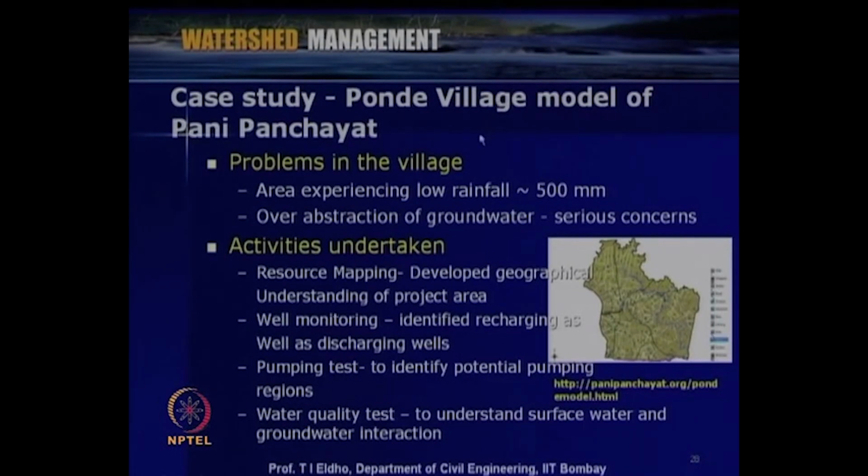So, within this Pani Panchayat, the activities undertaken were resource mapping, where they developed a geographical understanding of the project area, and then well monitoring, like identifying recharging as well as discharging wells, then pumping tests to identify potential pumping regions, then a water quality test to understand surface water and groundwater interaction and quality. So, these were some of the activities undertaken for this particular village.